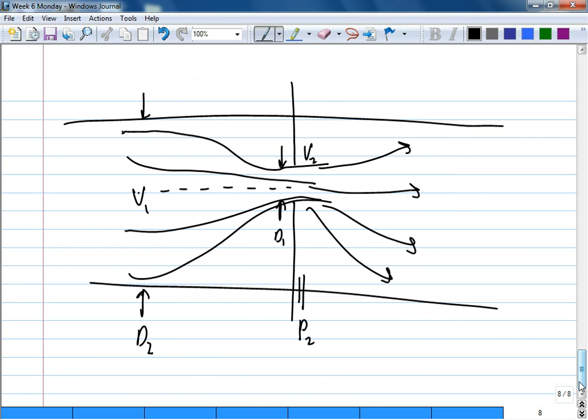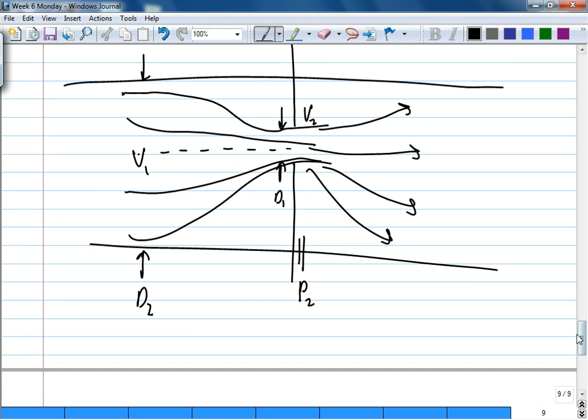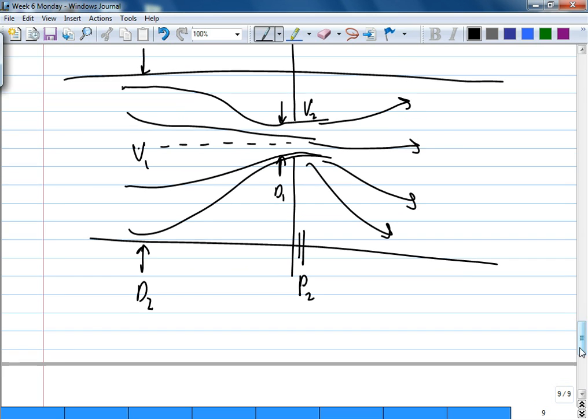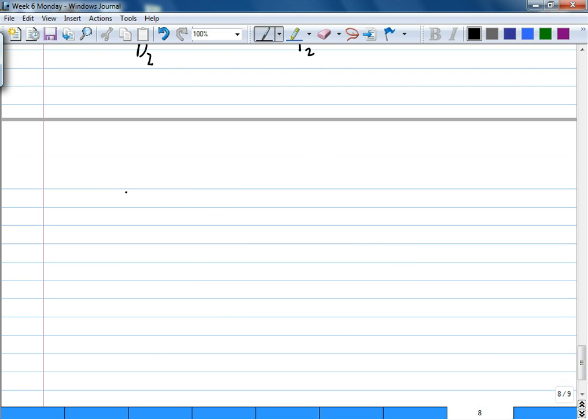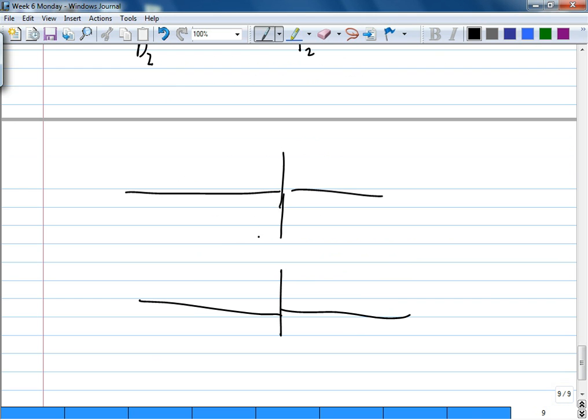Therefore, if you were to use this device and you wanted the accurate measurement, you will need to calibrate it and come out with something called a discharge coefficient. Before I talk about discharge coefficient, there's an in-between sort of arrangement. I think it's called a nozzle or vane or something. To try to help, in between the two devices, you still want to keep the cost down, but you want to get a bit better performance. Sometimes instead of having just a sharp hole, they have like a small nozzle, a small nozzle to guide the flow like that.